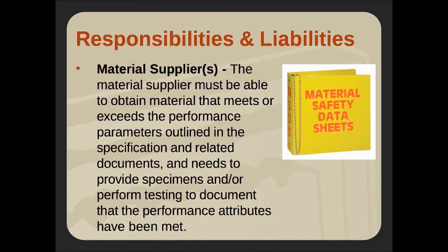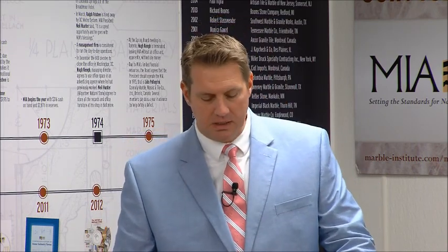Now, one thing I want to be clear on, the testing. I think it's important that we understand that most suppliers can acquire some basic testing data. It's not realistic to expect that a supplier is going to have the full litany of the 6 or 7 key ASTM tests that you might want if it's a high-profile job. So often as the specifier, if you're looking for the full litany of those ASTM tests, you want to be sure that you have that in the specification, so that the cost of them, which is high, is covered in the job.